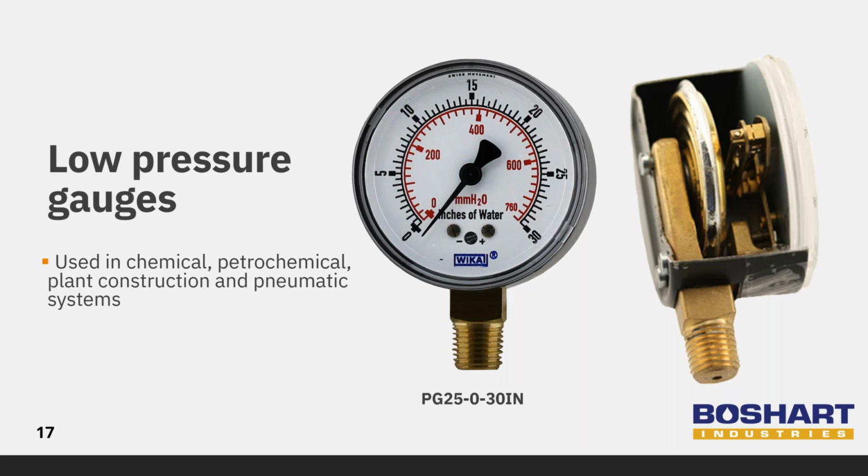The capsule on the pressure gauge consists of 2 circular metallic discs which mechanically deform as the pressure changes. Diaphragms are connected to each other and are tightly sealed around the edges with solder. The pressure is exerted on the inside of the capsule and is very sensitive to small changes in pressure. Extreme caution must be taken to ensure that these gauges are not overpressurized. The slightest pressure spike will damage the internal components of the gauge, ruin its accuracy, and make it unusable.